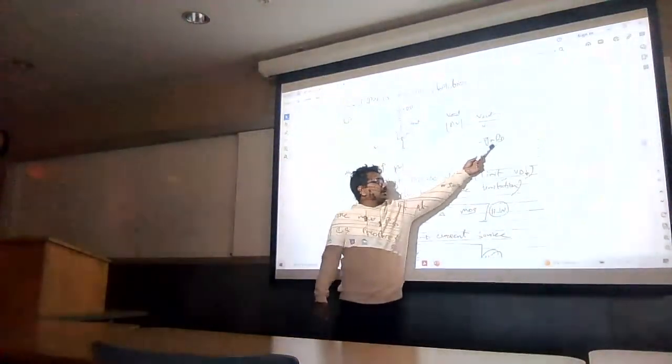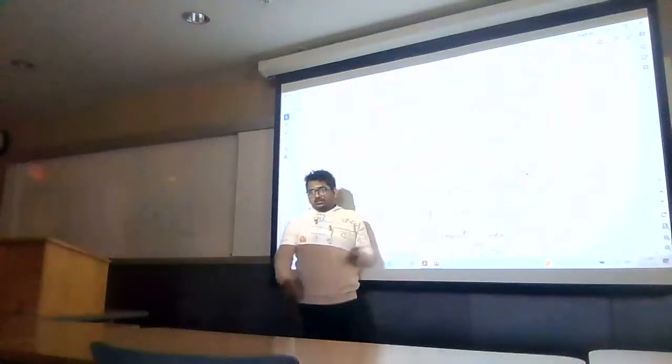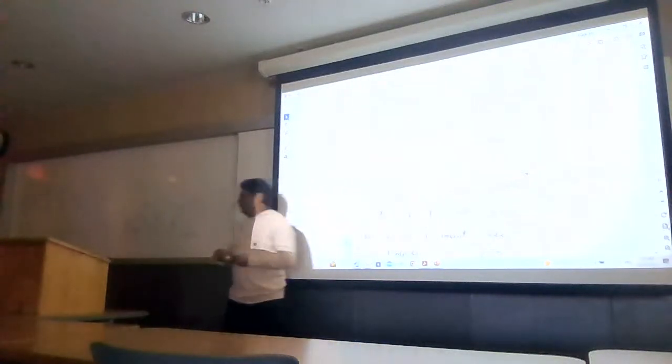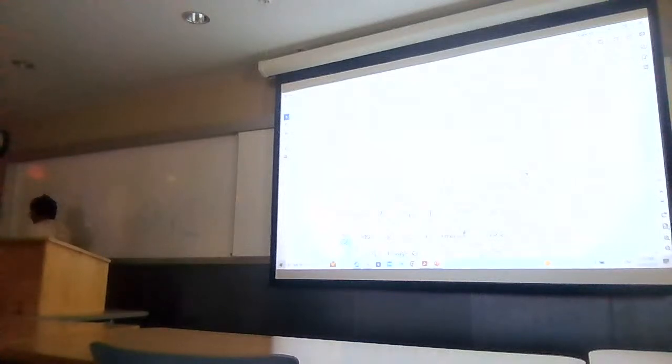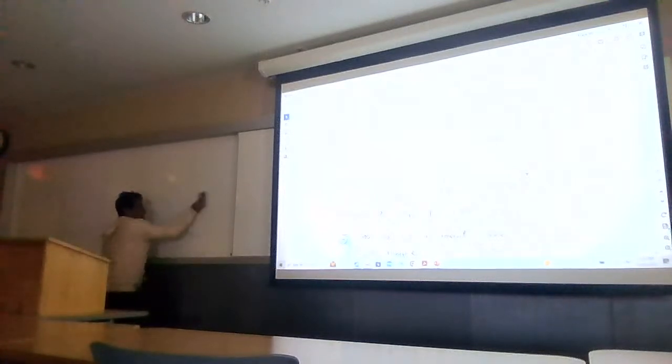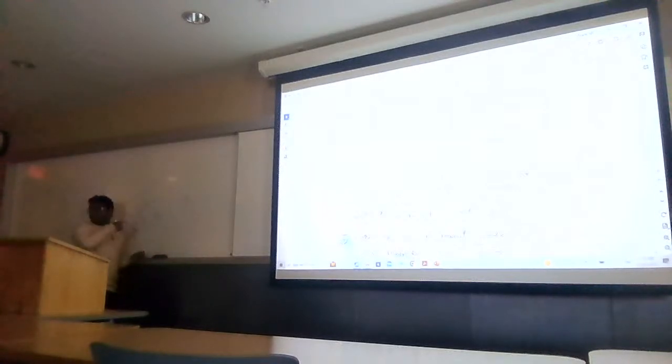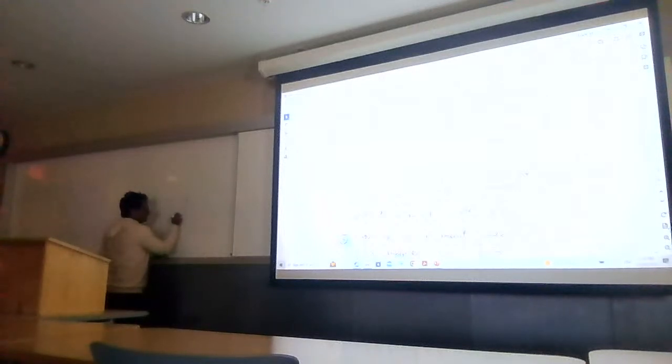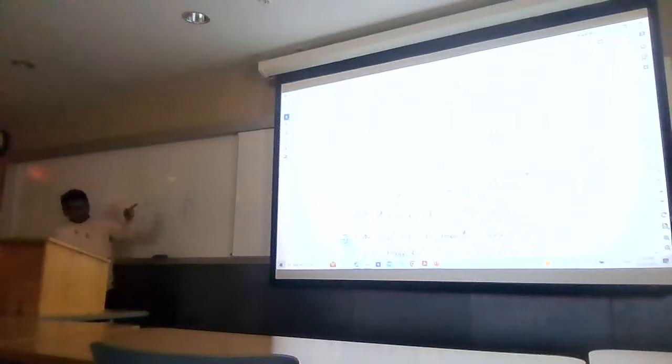Yeah, we can increase the RD or we can increase the GM, right? There are two parameters. Let's assume, you can see here, this is my amplifier, this is my input, this is VDD, that's the RD, and here is GM. This is my output. So my equation says if I increase the RD, then I can increase the gain, right?